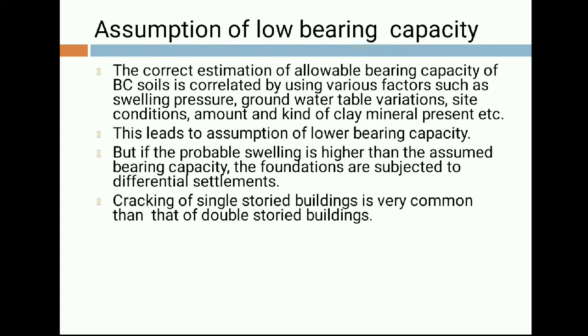Now, based on these kinds of properties of black cotton soil, it is always assumed that the bearing capacity of black cotton soil is low. The correct estimation of allowable bearing capacity of black cotton soil is correlated by using various factors such as swelling pressure, groundwater table variations, site conditions, amount and kind of clay mineral present, etc. So these are the factors which can influence the bearing capacity of black cotton soil.